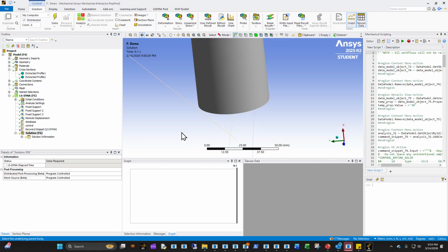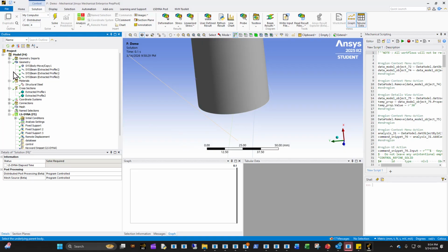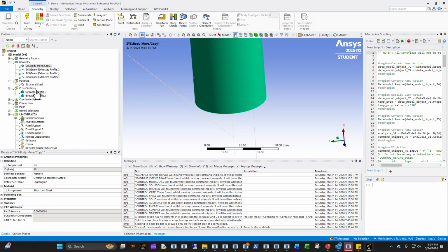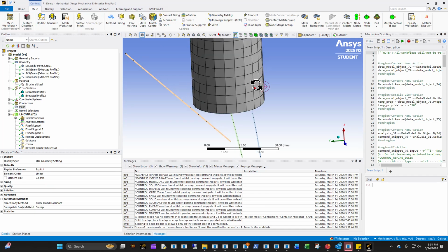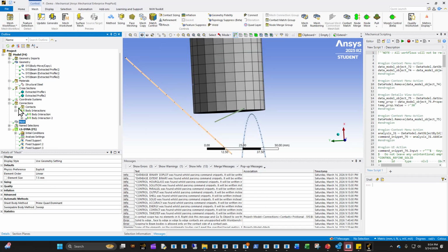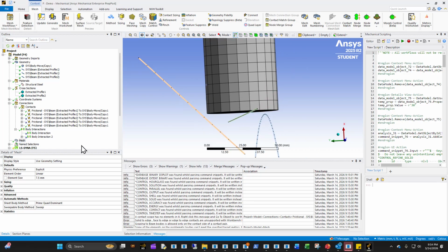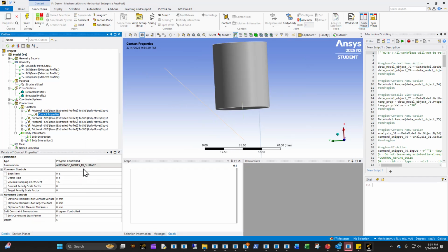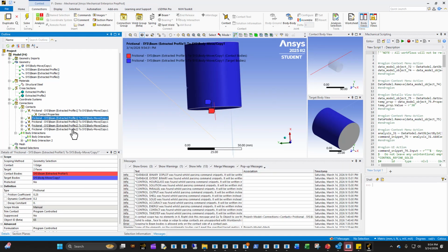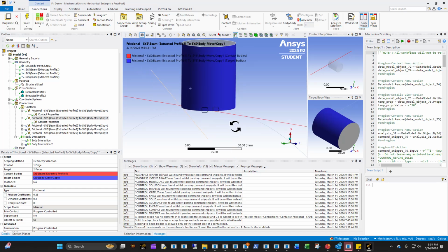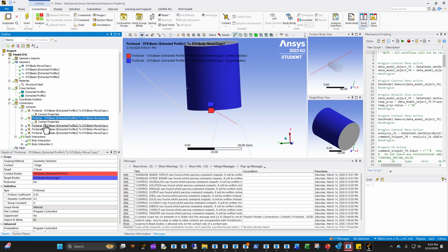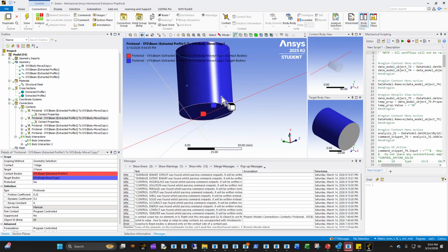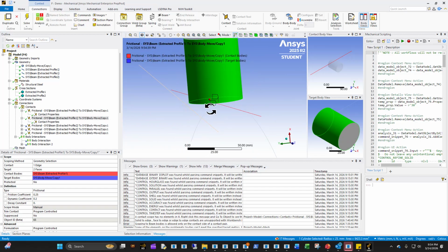edge contact correctly. As you can see, in this model, what we have are just 3 beams and a solid body. It's meshed like this, right? Nothing special to it. What I also have is several contact options that I can go over. Now for this contact pair, it's just an automatic nodes to surface contact. Okay, with the contact option here is automatic nodes to surface. This one is also an automatic nodes to surface, even though it has a straight edge and this one has a bent edge. It's the same contact behavior. The contact edge is basically these three faces, right, that I'm doing. These 2 faces that I'm looking at.